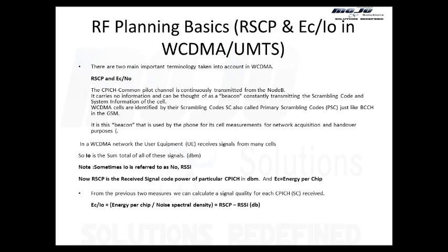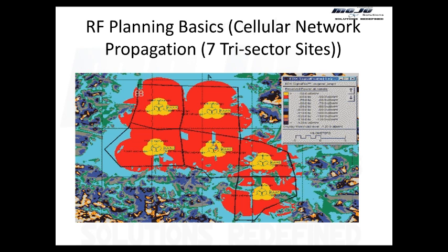One is from the other cells, because in UMTS and LTE, unlike GSM, many cells are transmitting at the same frequency, unless you add a carrier which transmits at a different frequency. So all the cells using the same frequency, the same UARFCN, will interfere with the UE.